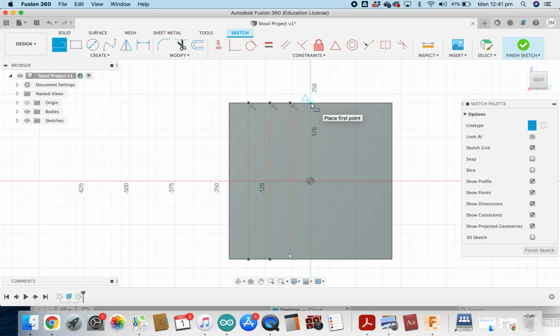We also want to do a midpoint line where we connect it straight down the midpoint of our rectangle. You can see that that line is black. That means that it recognizes that the line is in the middle of our piece of timber. And we're going to do another 3 lines on this side of the piece of timber. And we're also going to do one about 1/3 of the way horizontally at the top of our timber, and they're going to help us form the points that we need our timber to taper to. So they're called construction lines.